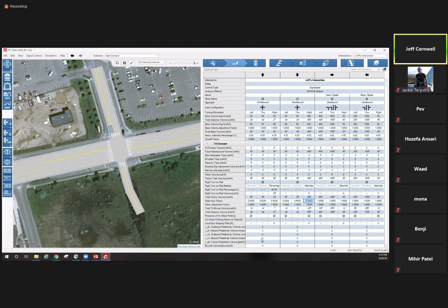So if the northbound left, actually, yeah, so the northbound left, turning left here, you're going to have inbound and outbound pedestrians, which you don't really know what they are based on the turning movement diagram. So maybe you'd split them in half and you'd put the numbers here. Let me go back to my diagram here.